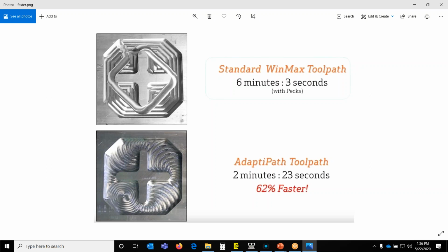What I would do on that type of application is probably program one of those frames as an open contour and make it extend out just a little bit past your circular pocket. Let it machine all of that away, and then just do a pattern to rotate it around. I think that is how I would do that.